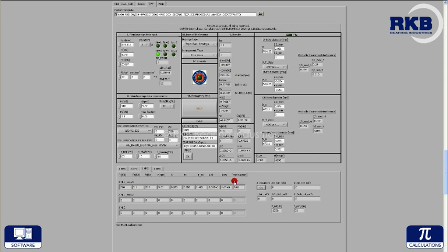All the parameters that influence the rating life calculations are displayed in the software interface, including actual kinematic viscosity at the operating temperature, reference kinematic viscosity required to obtain adequate lubrication condition, contamination factor, safety factor, and life modification factor. In the same way, the next 2 working condition cases are considered.